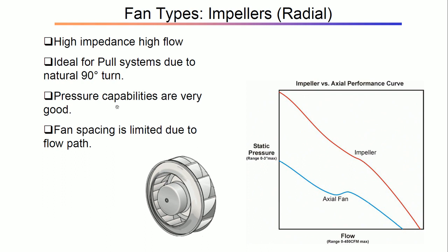The thing is, on pressure capabilities, for example, static pressure itself is twice as much, if you have a typical impeller radial fan and a reasonably straight curve compared to this. The advantage is similar power capabilities, but the cost is very high and the power also is maybe 2 times as much, because it is a product. While this fan ideally works in this region, this fan can work in a very wide region. So, the total area under this is approximately 4 times as much.